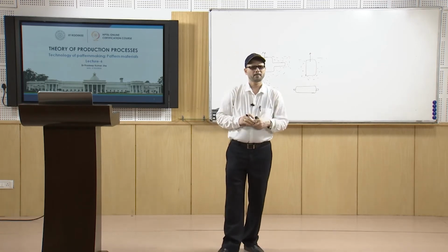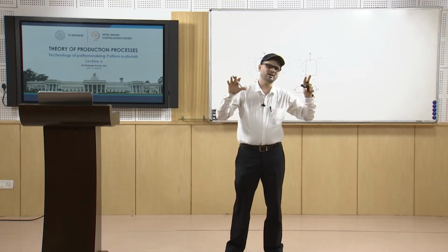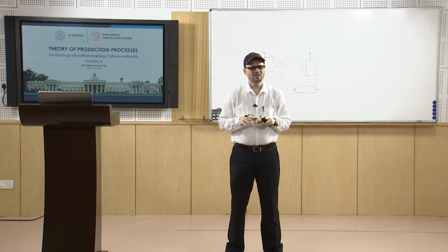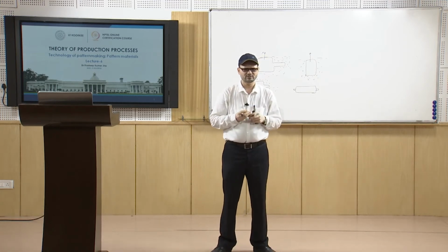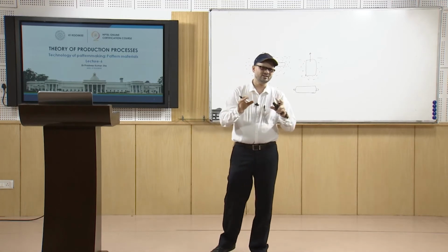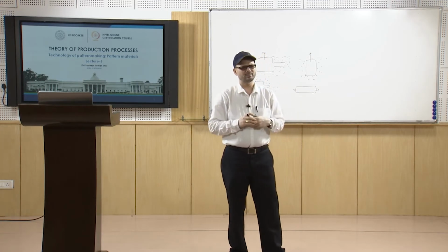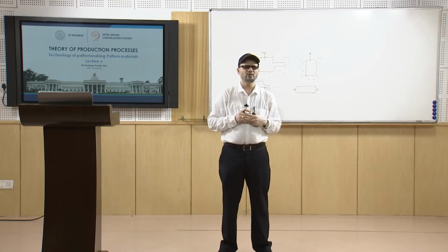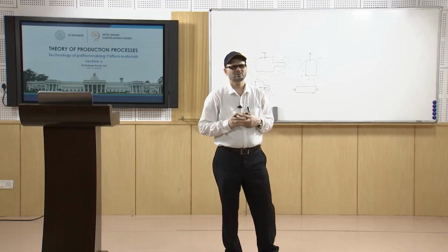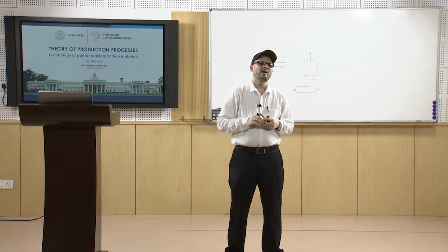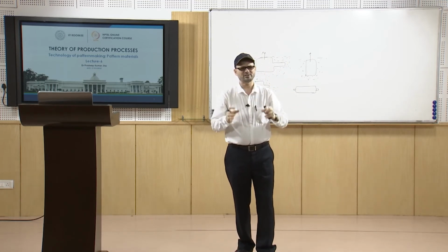Dimensional stability. The pattern material must be dimensionally stable. We know that depending upon changes in conditions, dimensional changes occur with the change in weather conditions and with the change in temperature. There may be changes in the dimension of the material. So, you must select a material which is dimensionally stable. Mostly in case of wood, it is seen that with seasonal changes, there will be variation in its dimensions. So, you should make sure you have a material which has dimensional stability.